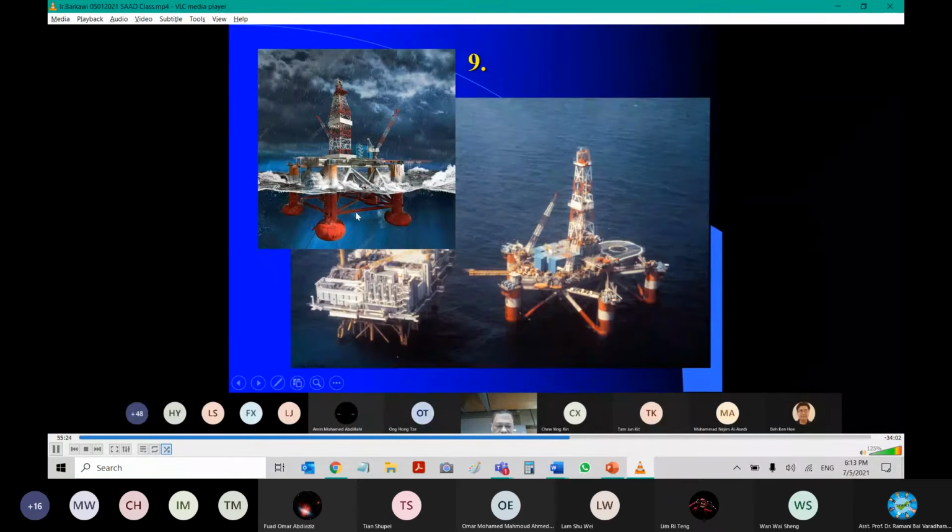And it is connected to this, what we call tubular joint. This is the leg, and this is the joint. This is a K joint, basically. Okay, so it is not anchored to the bottom of the sea. It's just floating like that. So the external forces will be the fluid forces or the buoyancy forces based on Archimedes principle, and sometimes you've got waves as well.